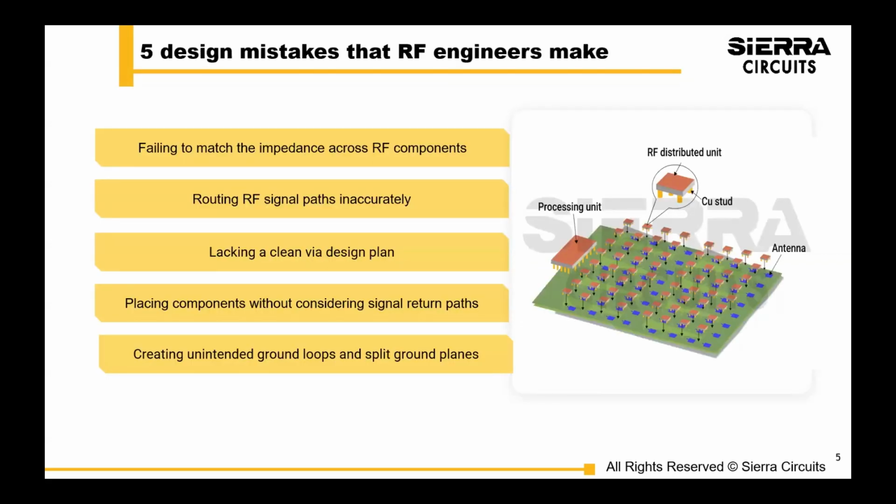So let's start with some high level, common mistakes RF engineers, or basically any engineers getting into RF, can make during their layout phase. Definitely RF is a journey and there's definitely lots of prototyping that happens. So try and take what you can from this webinar and presentation and our design guides and hopefully improve your journey. So, you want to make sure that, of course, you match impedance across the RF components. If you don't, you can get reflections and signal loss.